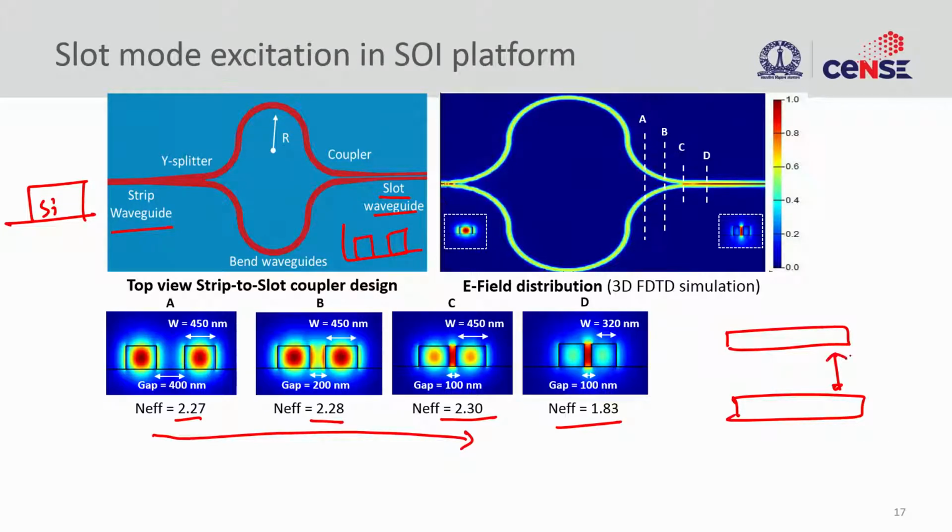This is exactly what we discussed in our directional coupler. You will have individual modes, but when you bring them closer and closer, you will have supermodes. And these supermodes will have a higher refractive index than the discrete normal solutions that we have in the individual waveguides, and that is exactly what we see.